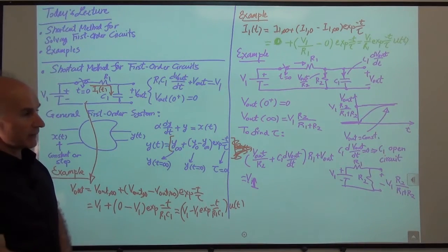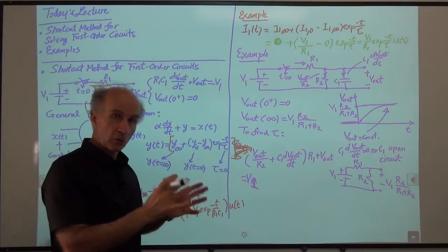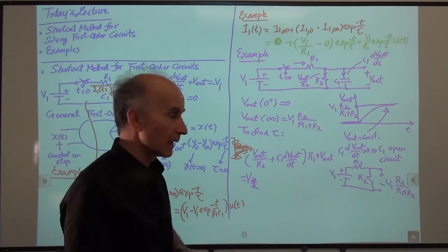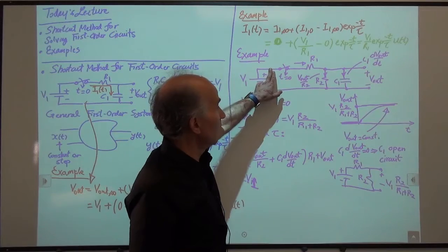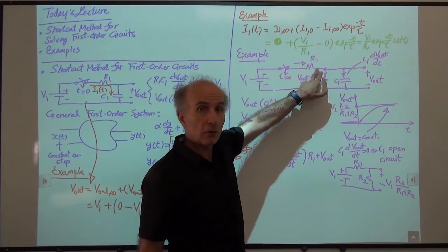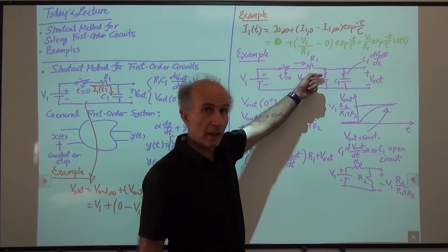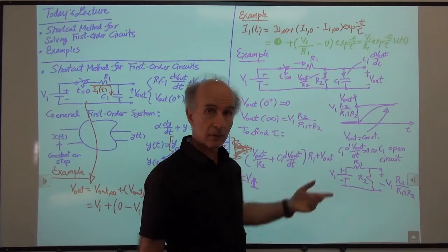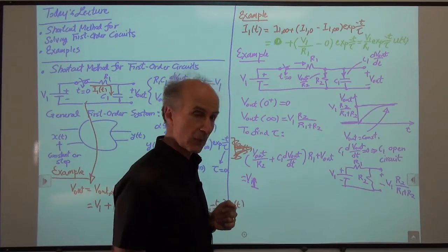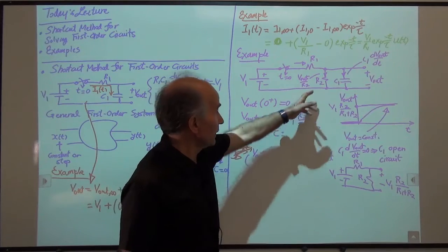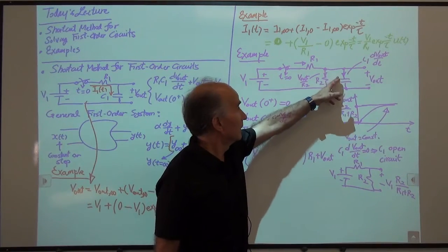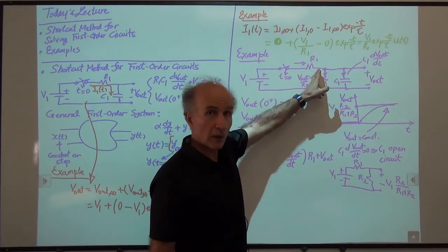So let's take a moment to understand how we wrote this equation. As I said, you can also write it in the usual nodal equation form, because we can say V1 minus V out over R1 is this current, and then equate that current to these two. It's the same thing here. So this says this current added to this current gives us the total current flowing through R1.